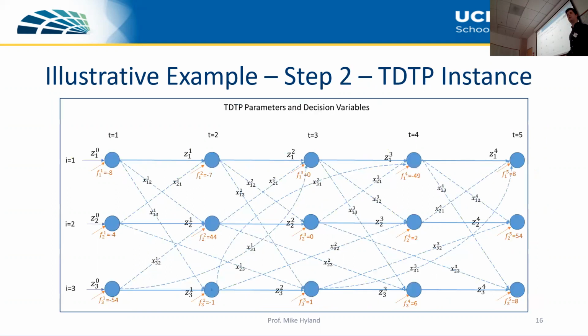So we need to process this kind of raw input into the inputs we need for our formulation, right? What we need are these f_it values, which are the relative imbalance of flows going into and out of these nodes, where our node represents a zone-time pair. You can see we have positive values and negative values. Notice that on the left-hand side, you tend to have negative values, because this is the start of the day. You only have trips leaving these zones. And then towards the end of the day, it tends to be positive because most of your trips are terminating at a particular zone.